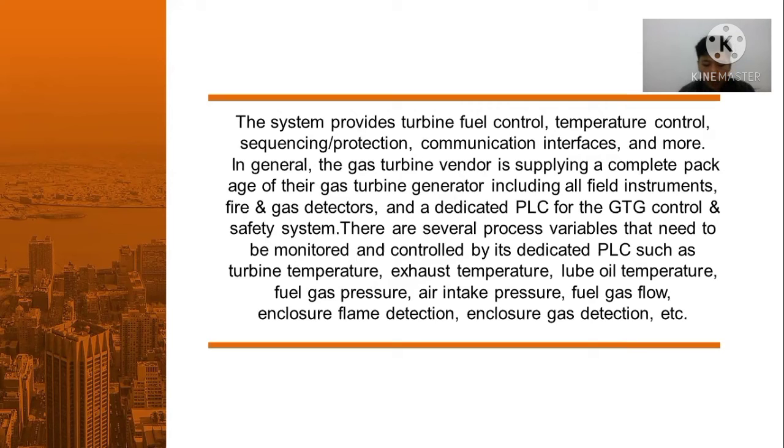There are several process variables that need to be monitored and controlled by its dedicated PLC, such as turbine temperature, exhaust temperature, lube oil temperature, fuel gas pressure, and intake pressure, fuel gas flow, and enclosure flame detection, and enclosure gas detection.